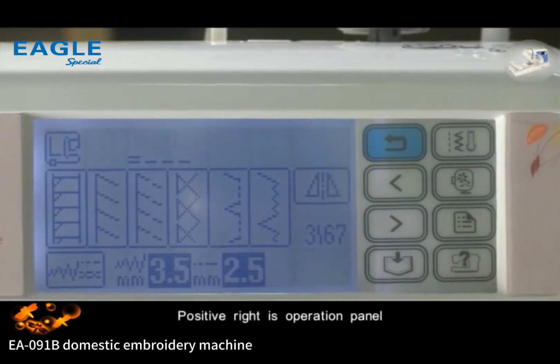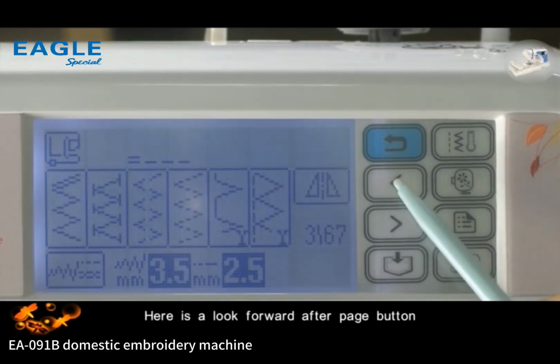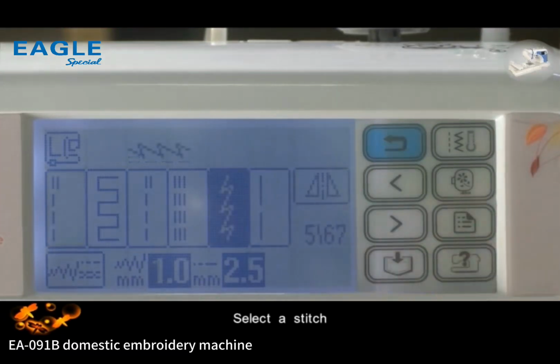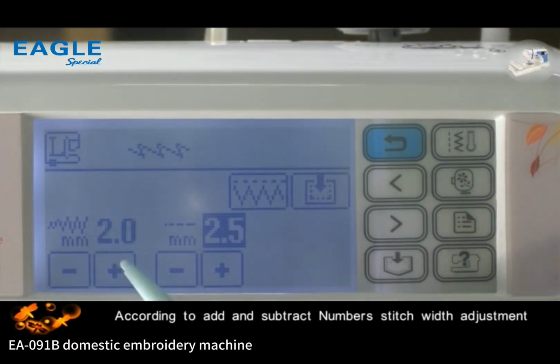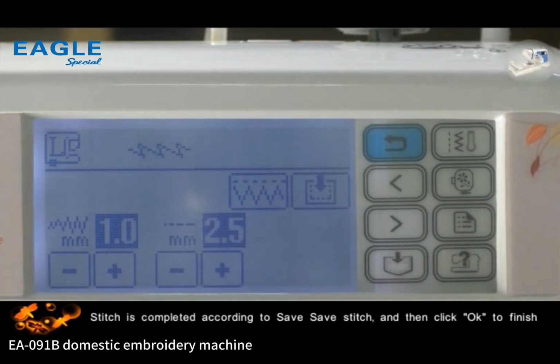On the front right is the operation panel. Here is the forward and back page button. On the left is the LCD screen. Select a stitch. Press flip horizontal to reverse it. Enter the stitch width adjustment, press add and subtract to change the numbers. Stitch length adjustment, also with add and subtract. When the stitch is completed, press save stitch.